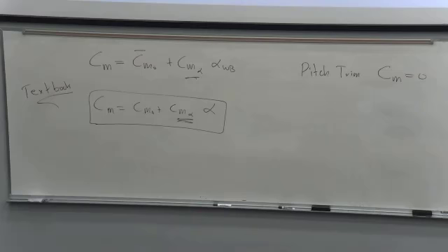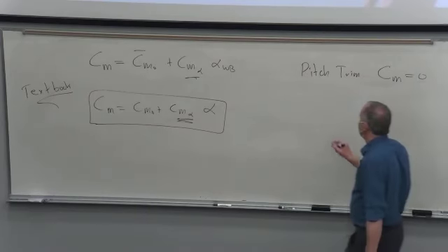One of the ways that we can adjust things is by changing the tail setting angle here, because everything else is geometry. So we can tilt that tail up and down and either create an up force or a down force to balance out the other half of it. So we said, yeah, we can do that, and we drew a picture about it, right? So then the next thing is pitch stability.